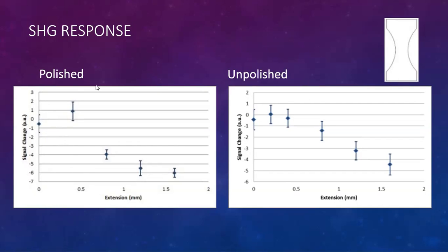For both a polished and an unpolished sample, we see a significant decrease in signal once it gets more and more damage in that plastic region, soon to being able to crack and fail. The reason we did polished versus unpolished is because unpolished is obviously what we prefer. If we don't have to polish up our nice airplane to test it, that saves us time, money, resources.